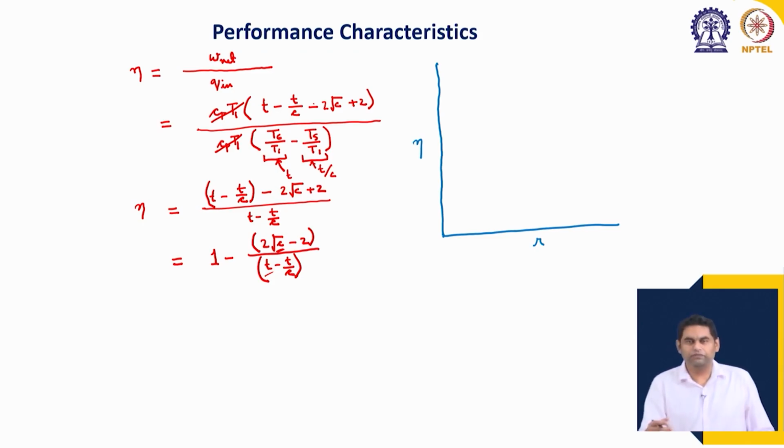And we also know that when regeneration is added to a cycle, the behavior of the efficiency curve changes completely, and the efficiency behaves in a different way, where it decreases with increasing R. So, this is R equal to 1, which is the minimum theoretical value of pressure ratio. Now we will draw some reference curves.